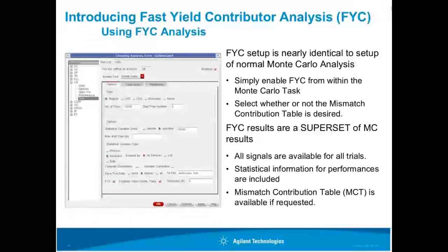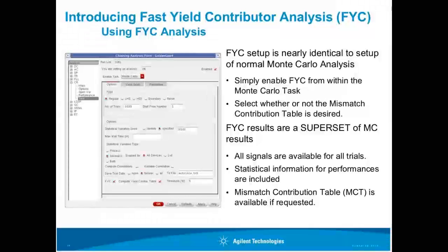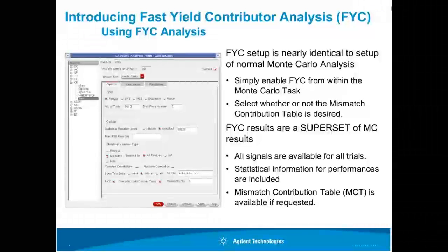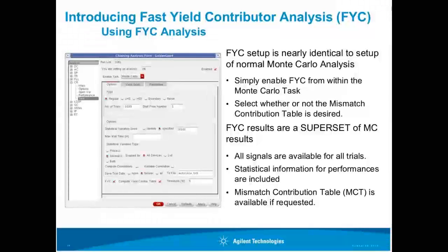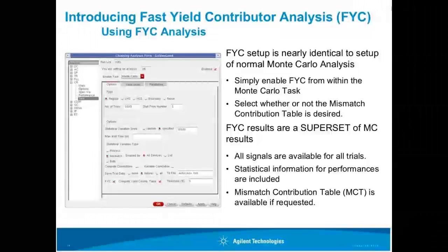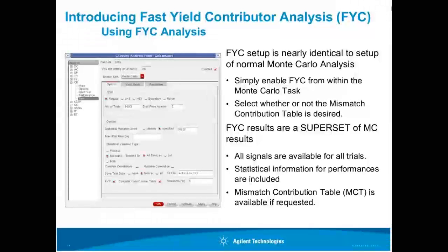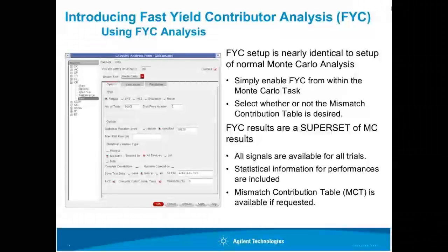But if that process parameter doesn't vary very much, it's not a problem for you, because high sensitivity alone isn't the issue. The issue is higher sensitivity and a higher amount of variation. So what this brings to the table that sensitivity doesn't give you is an overall view of your process and how much variation is in there.